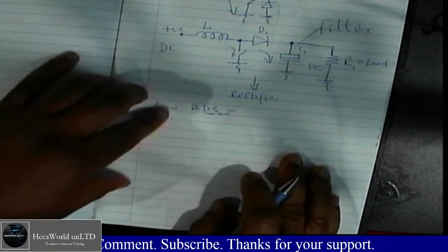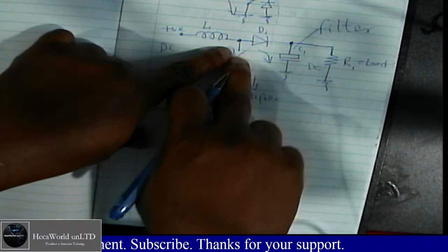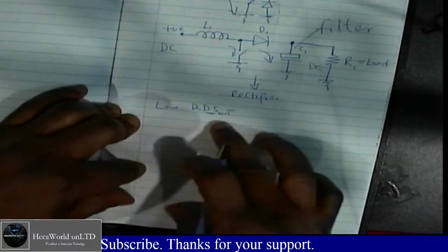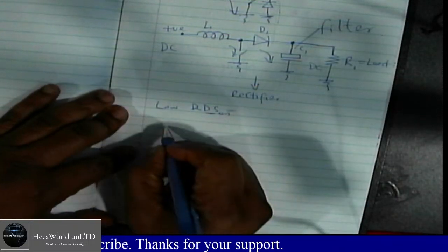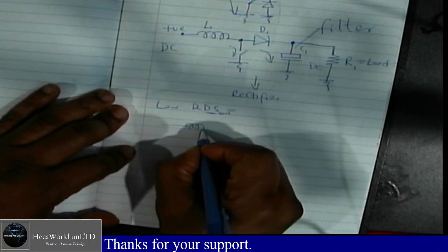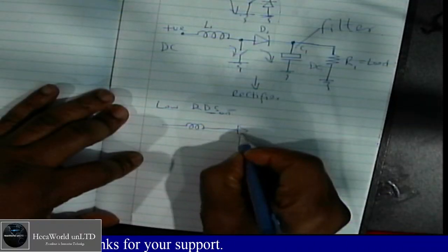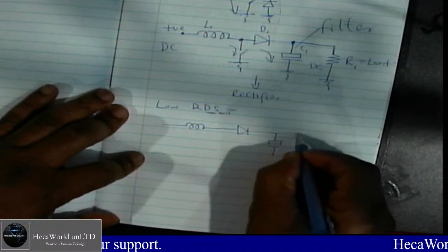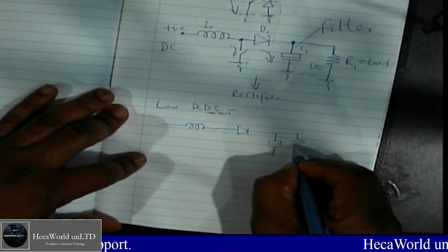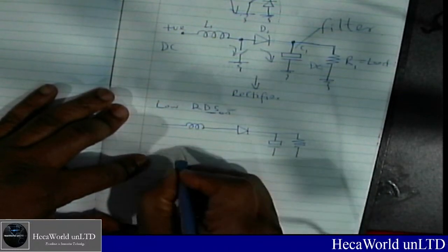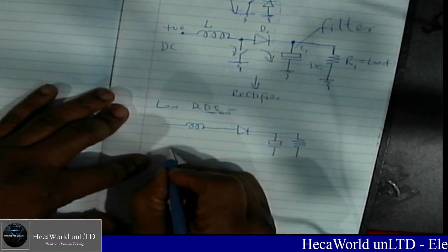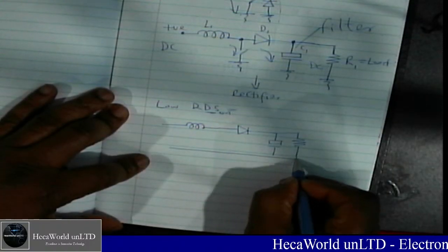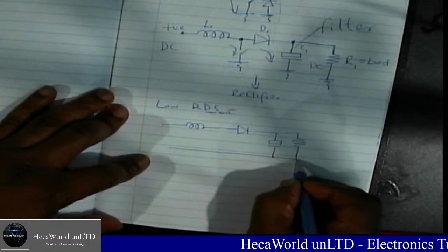Let me now redraw the circuit and replace this switch with a MOSFET. You have a space here to do that. So remember, you just need an inductor, a diode, a capacitor, and a load. This load we can leave it for now because we can just use a multimeter to measure the output.